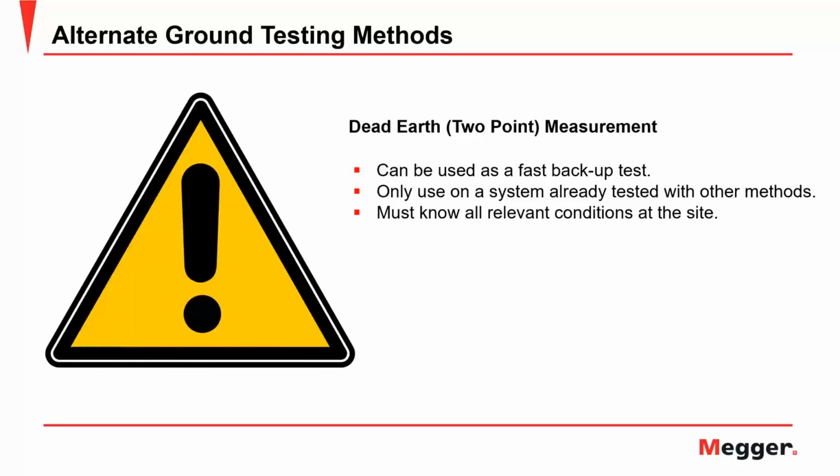But if you have third-party involvement and somebody's demanding that you submit some sort of test result, then at least you can cite IEEE 81 as at least giving mention to it and defining the limits of the reliability of the test.